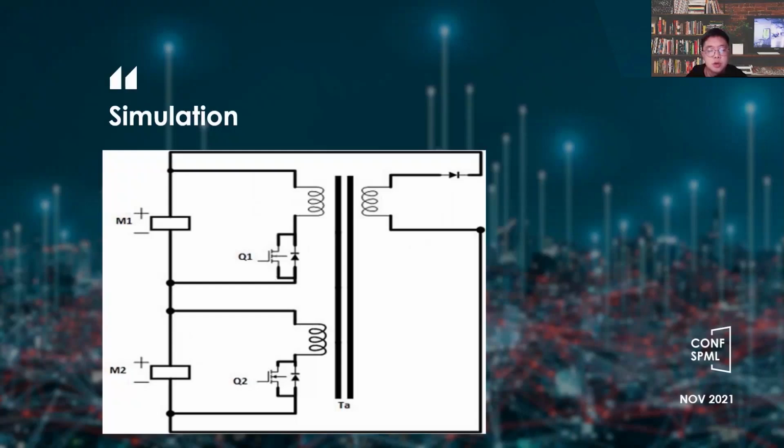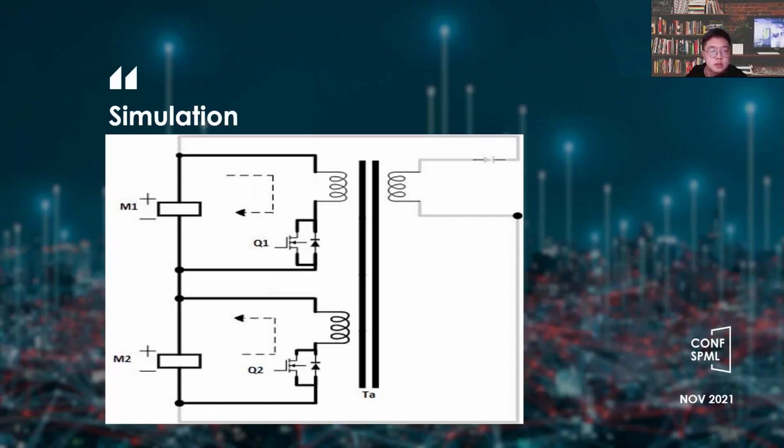The transformer equalization topology realizes the charging and discharging state of the equalization unit through flyback conversion, thereby realizing the energy equalization between two adjacent battery modules. Yes, this is the circuit when both MOS transistors Q1 and Q2 are turned on. When VM1 is bigger than VM2, the module M1 discharges, M2 charges, and the current of the primary winding connected to Q1 rises and stores energy, and the current of the primary winding connected to Q2 rises in the opposite direction and releases energy.